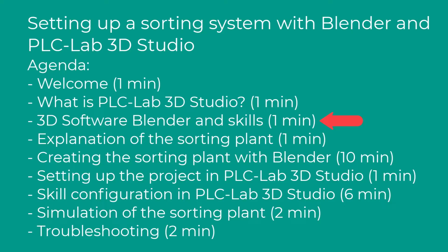First, the MHJ Asset Library. This is a toolkit with ready-made 3D objects like conveyor belts, cylinders, sensors, or buttons. Everything's included. The trick is, these objects already come with their basic function, or skill. A skill is, so to speak, the ability or role of an object in the model. For example, transporting, detecting, or moving.